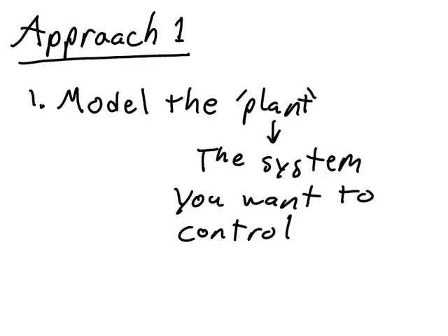For example, if we were using approach number one to find good control gains for our motorized potentiometer, we would start out by creating a model of all of the parts that are inside of that motorized potentiometer. Our model would include an equation to describe the behavior of the motor. It would also include any effects involved in the belt that transfers the motion from the shaft of the motor to the slider, and it would also include friction effects.